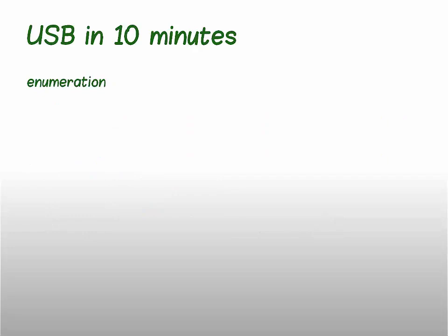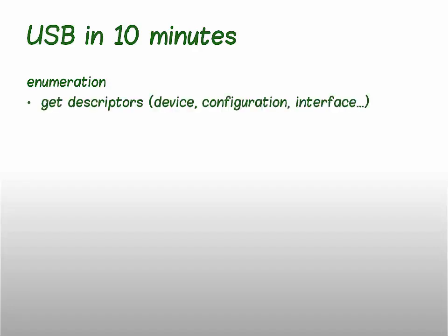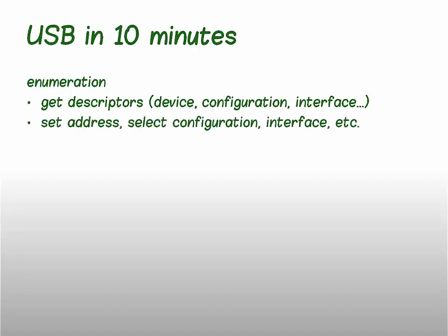When a device is attached to the bus for the first time, the host starts to request descriptors from the device. Descriptor is a data structure providing host with information about the particular device, such as the maximum data packet length. There are many different types of descriptors. When the host gathers the necessary information from descriptors, it assigns an address to the device, configures the device as appropriate, and can start data transfer as needed.